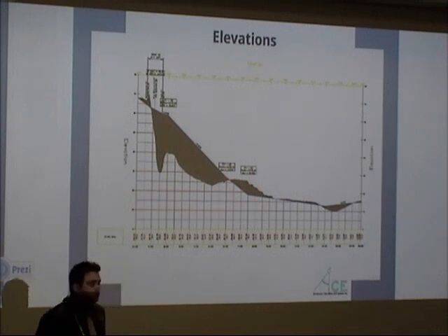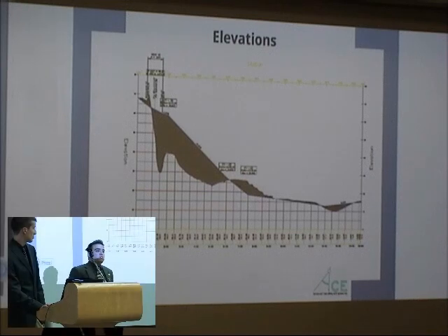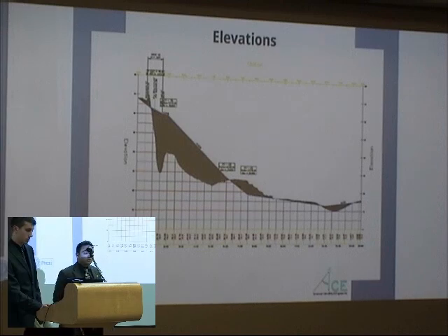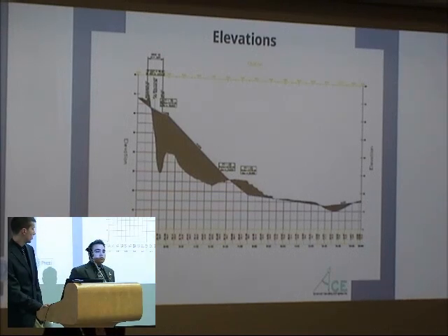During this transition, the super elevation of the road is towards the right, to draw the water to the right into the little hole. After meeting the height and grade 1% on the parking lot, it runs at 1% all the way through the system of the road. At station 1300, you can see that it raises up again. It's still at 1%. This is because it's the rotary on the end of the road. This is done so it can latch back into its height when it comes back.